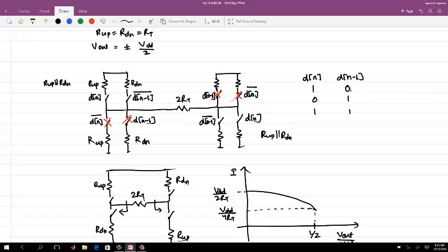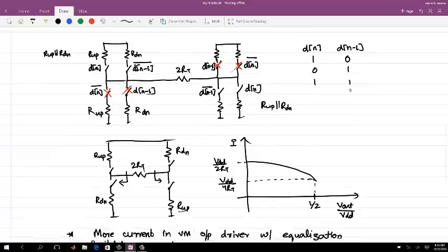What would you do? I mean, how will you design R up and R down? And take a simple case right now, PMOS over NMOS. Okay. You use a lot of segments and you choose between them. So let's just start with that example.